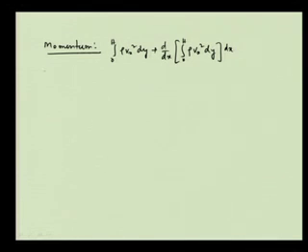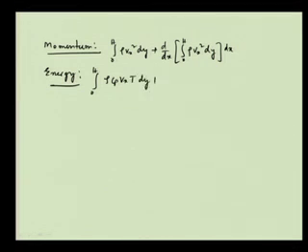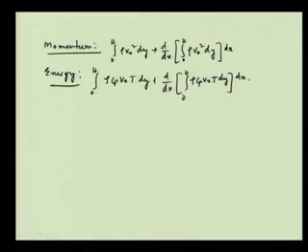And then the energy, in exactly the similar way, would be the integral from 0 to h of rho C p v x t dy plus d dx of the integral from 0 to h of rho C p v x t dy, whole into dx. That is the energy out through plane 2.